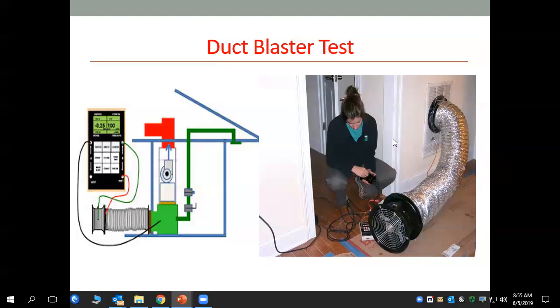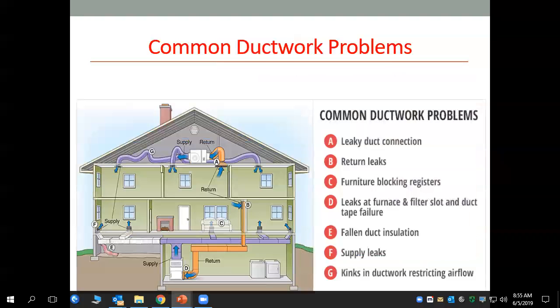If you use it with the air handler, you get a little more allowed leakage, but your air handler furnace is one of your greatest sources of leakage. The manufacturers say that the leaks are 2% or less. I'm just not sure what their percentage is based on. I've discussed that with them before, and I don't really get a good answer out of it.